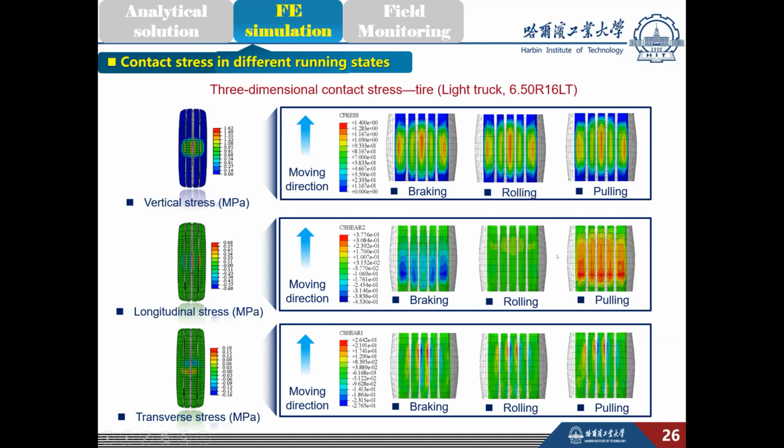But when we analyze the shear stress and strain, we can observe that the peak values in all 3 directions are influenced significantly, which means the existence of horizontal contact stress cannot be ignored in the calculation. This could be used to explain the failure or top-down cracking mechanism in some situations.